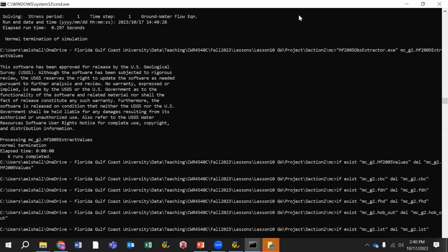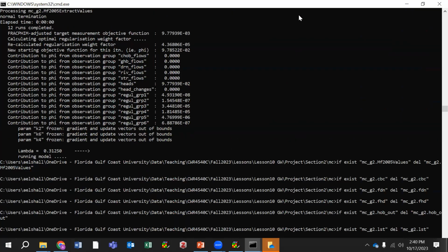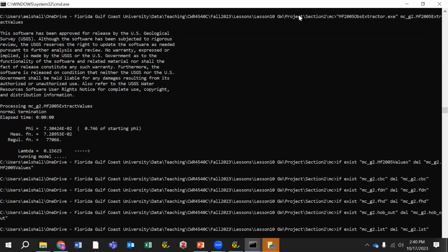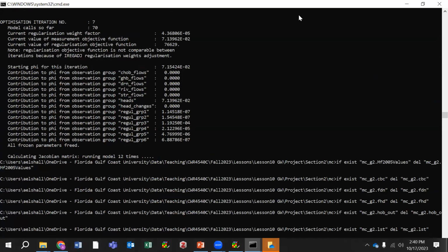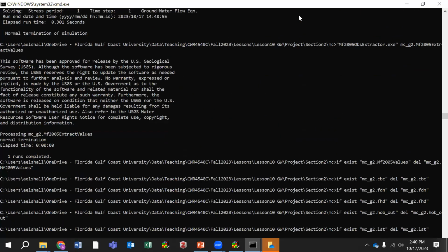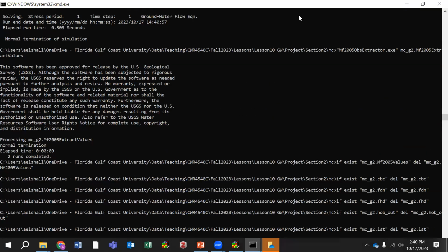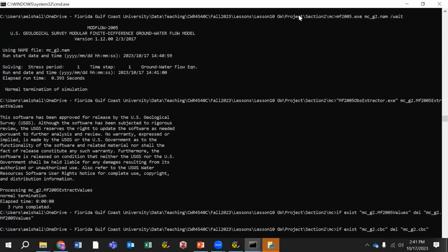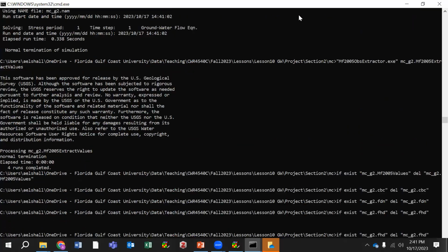The constraint is that the strength should not go below this one, but play with all the other ingredients to reduce my cost. The optimization would change the mixing ratio, then calculate the strength and the cost based on this mixing ratio, and keep playing with this until you get the minimum or maximum profit, or whatever you are doing.